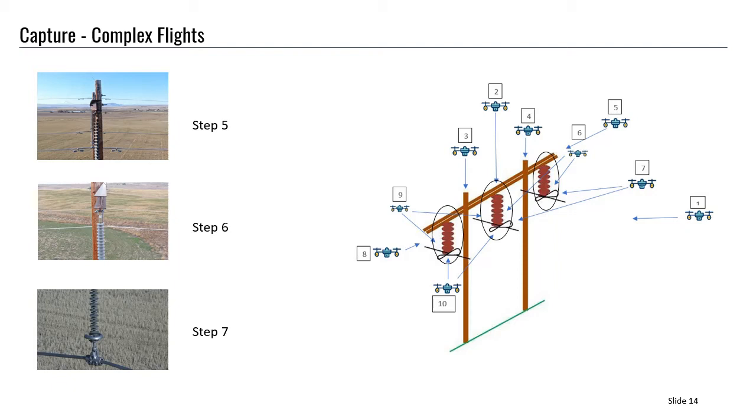Position 6, outside the insulator arm, you will need to maneuver so that you are getting a clear shot of the end of the pin that has the cotter pin in it. Position 7, the lower end of the insulator with a cushion grip and its pins. Inspect the insulator sheds as you are maneuvering the camera around the insulator.